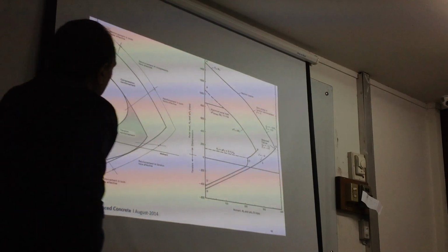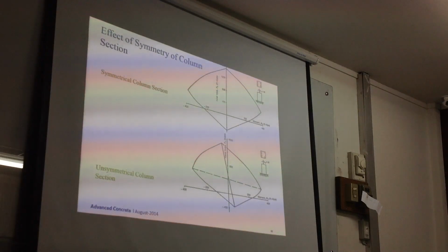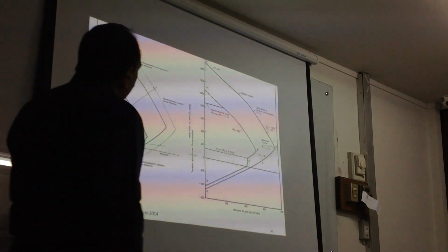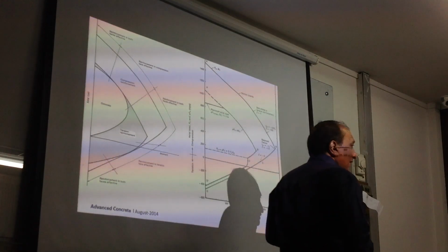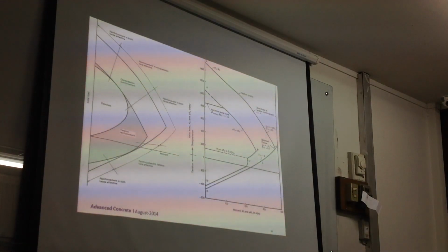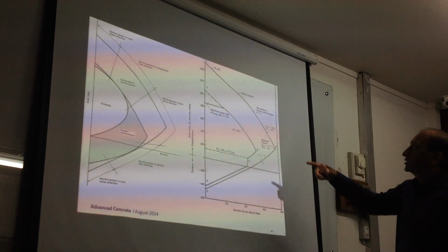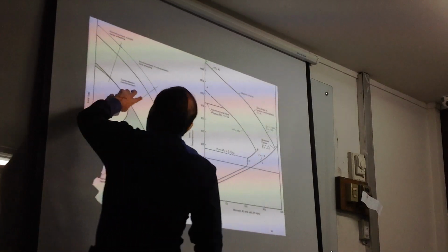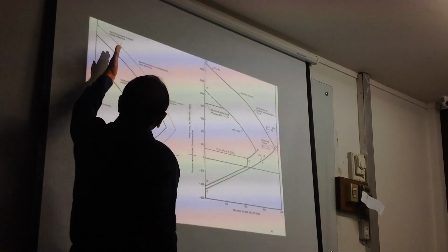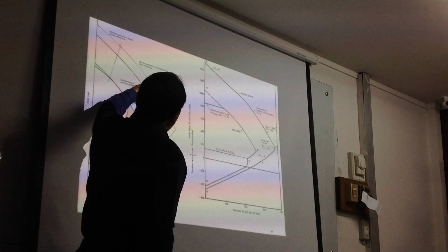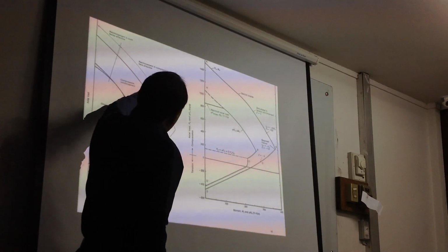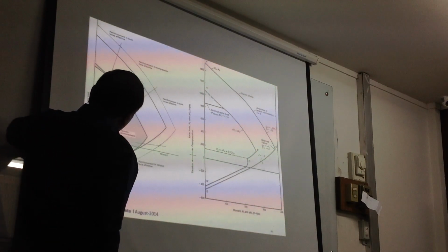There are various ways to look at the interaction curve in a little bit more detail, to relate it to the stresses in the reinforcement, to relate it to the stresses in concrete, and so on. And why? You might wonder, why do we need to worry about this? Because if you look at this curve, you can read in your slides more clearly, this portion is governed purely by compression, and this portion is governed purely by tension.